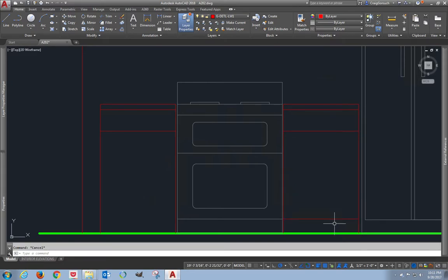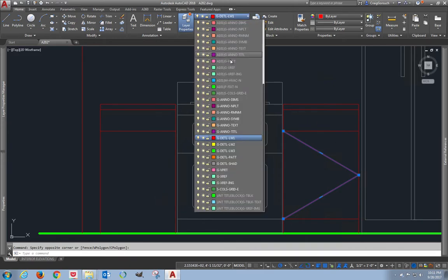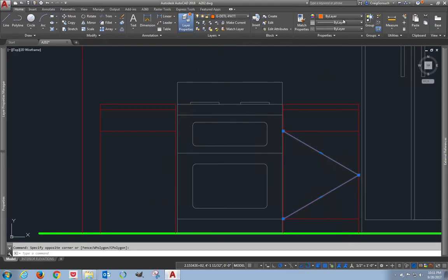So I'm going to draw a temporary line, that, and another one here, because I want my polyline like that. And I can delete that, highlight that line, come here, change it to the pattern layer, change this to hidden 2, and then mirror it right across there.